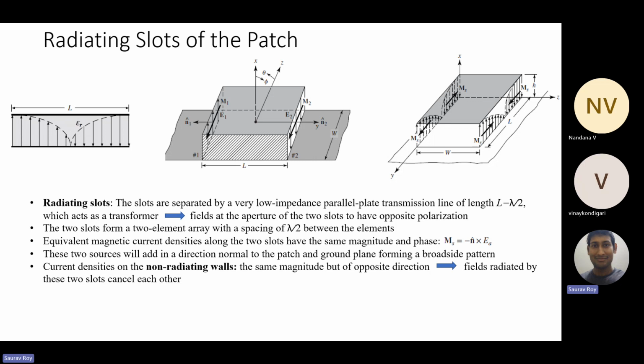So when I'm inside the surface only, these two half cycles lead to EMFs, and these two have opposite direction current sources. So that will obviously cancel out. That's why the radiating slots separated by W cancel out these magnetic sources in one slot only, so they don't lead to any radiation. So only the radiating slots separated by L.